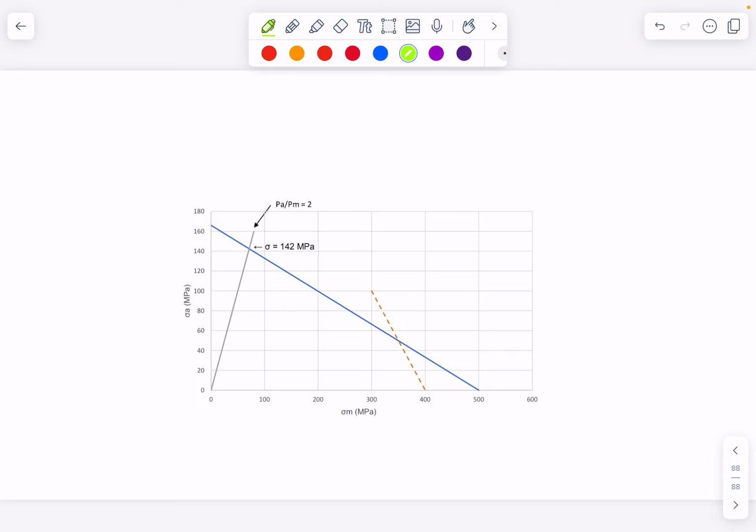So again, on a Goodman diagram, we've increased what our endurance limit is, still come down to the same ultimate, we've still got the same ratio through here, so it allows us to work up to there instead. So again, very, very quick traipse across fatigue. It's a really large and critical area, but it gives you the basics of it. Okay.